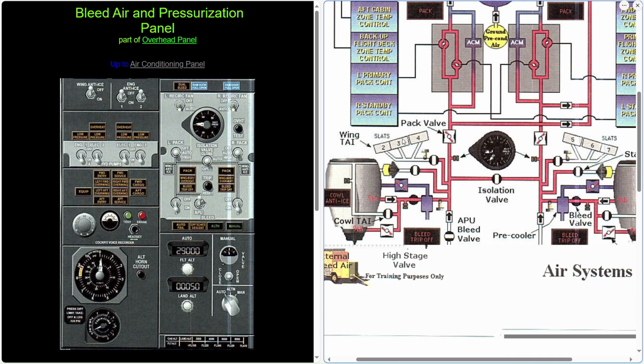And that heats up the leading edge of the wing, so there's no ice forming on that, and that's how the bleed air is taken to heat up the leading edge, because this air coming from the engine, remember, it's coming in fifth stage, it's very hot, and in ninth stage, it's very, very hot. Now, of course, there's more pressure here than here. There's a lot of pressure here. There's an awful lot of pressure here. So that air goes up to there. Then we start going in.